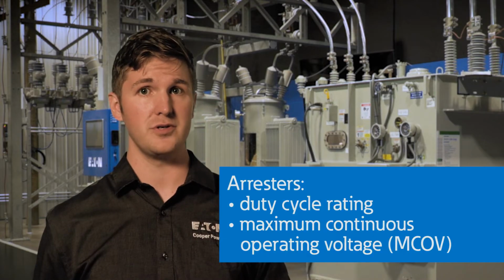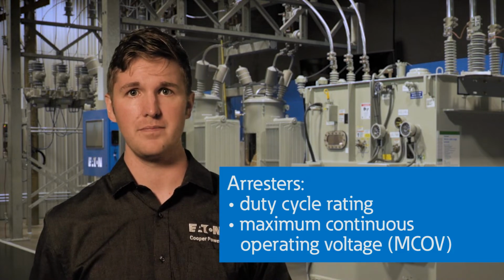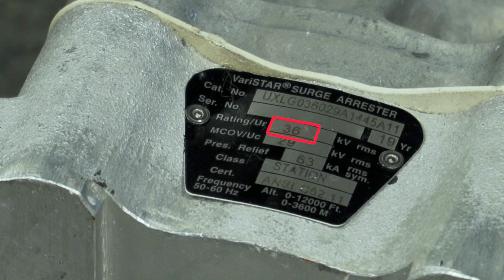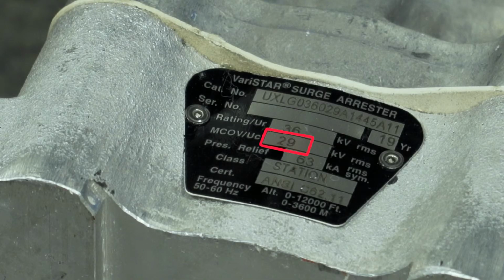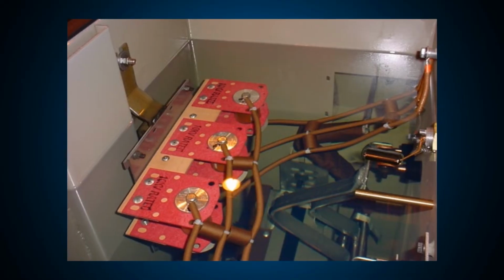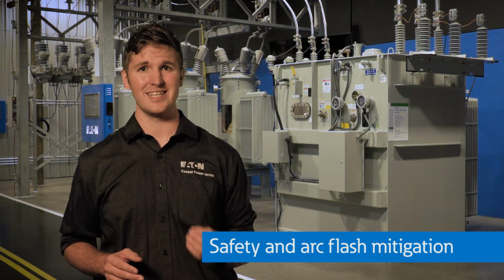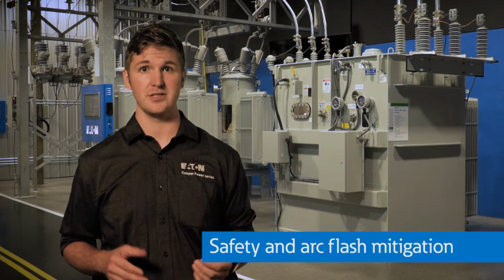Arrestors are defined by a duty cycle rating and a maximum continuous operating voltage, or MCOV. The duty cycle rating indicates the ability of an arrestor to withstand repeated voltage surges on the system. The MCOV rating is the maximum voltage that may be applied continuously to the arrestor. Arrestors can be located external to the transformer tank in live front or dead front styles, or in the transformer tank under oil.